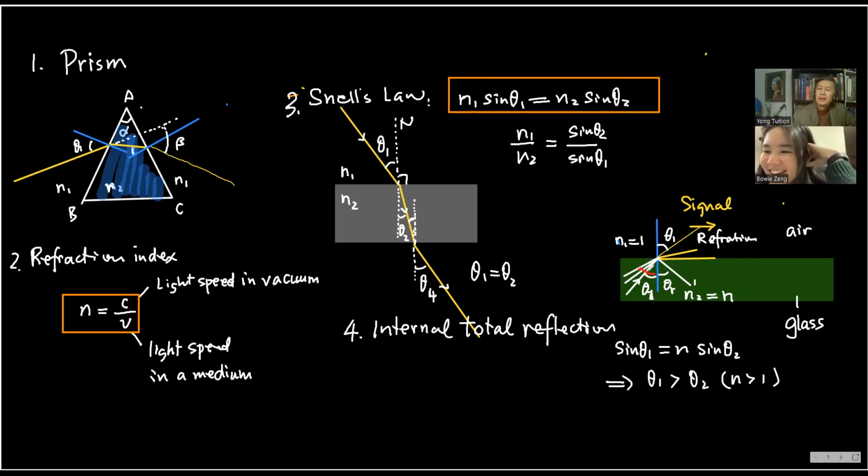That's why we call it total reflection, because the refraction is transmission, you see. If the refraction goes through the cable fibers, which means that there is transmission. No transmission means no loss. Does that make sense? So that is why we wish to work out this angle. The red angle is called the critical angle.